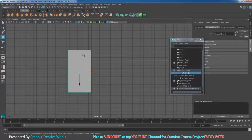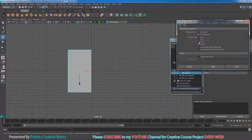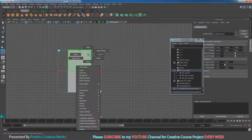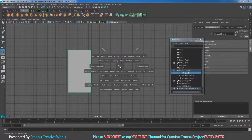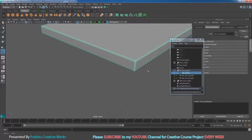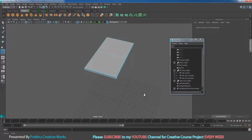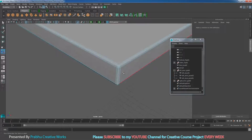So when your object selected, go to UV and choose planar option box. You want to keep the same settings and choose project. Now right click and choose object mode. Now go to perspective view. So listen carefully. So now right click on this corner edge over here. So and choose edge mode.